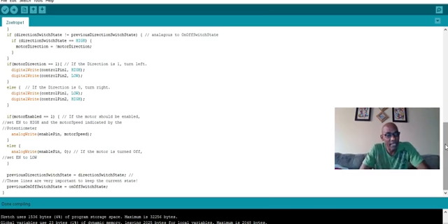But the main takeaway here from this project is the ability to have your motors spin in two directions, clockwise and counterclockwise, and the knowledge of using an H bridge and what an H bridge is, right? So an H bridge is a circuit in itself. It's a circuit, when you use an H bridge in your circuit, it's a circuit within a circuit, all right? And like I said, the H bridge here has four switches.